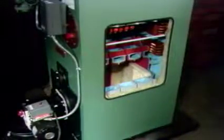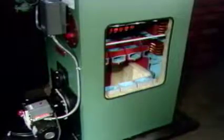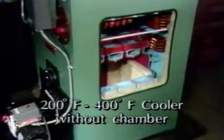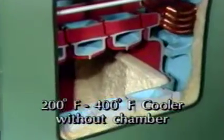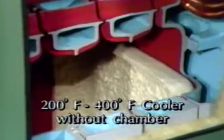But what about an appliance like this? It's a wet base boiler where the burner is fired with a target wall. Here, flame temperatures can be as much as 200 degrees to 400 degrees cooler because heat is radiated to the surrounding water-backed surfaces, providing excellent heat transfer.